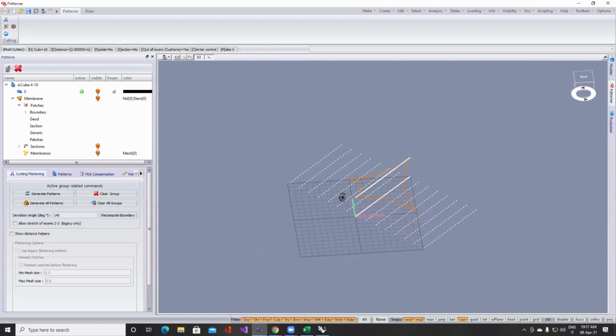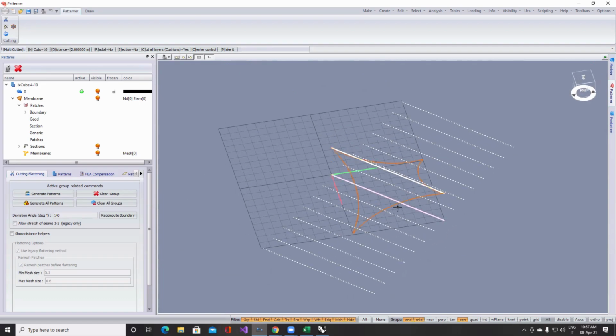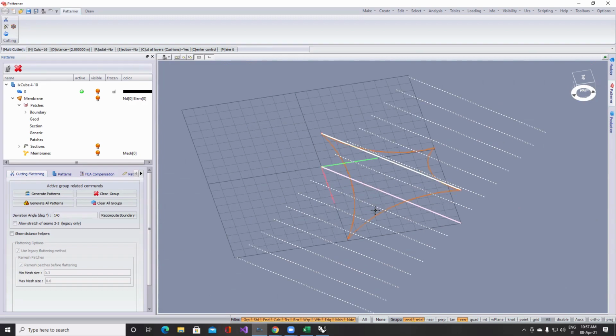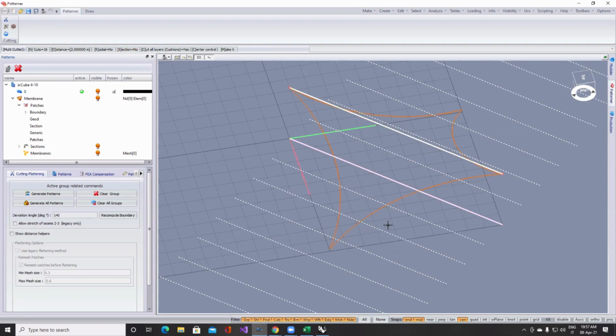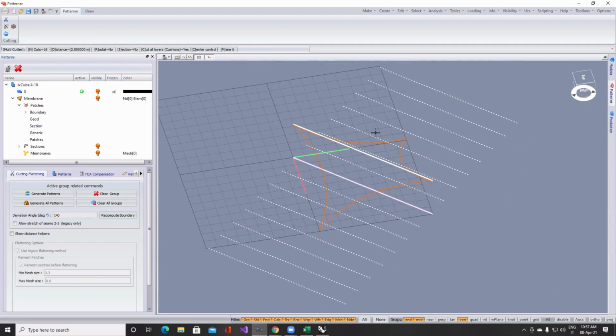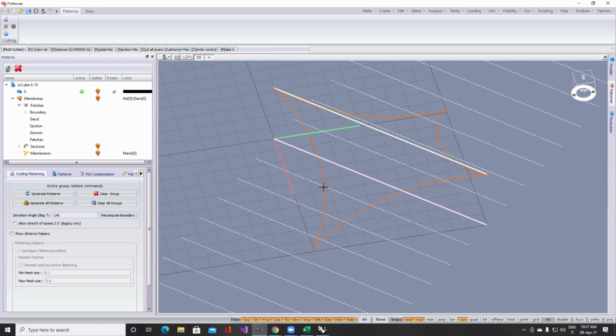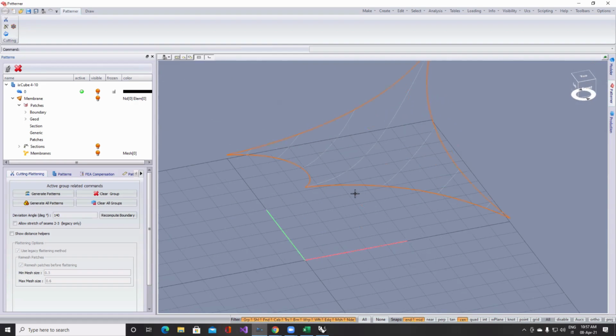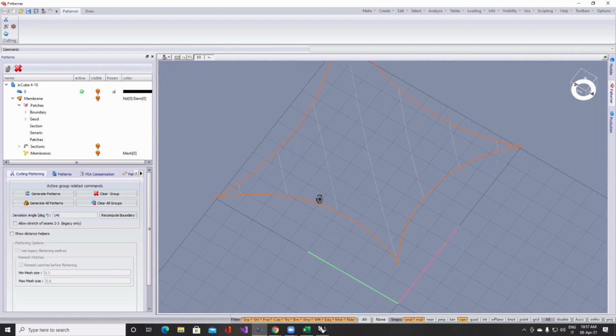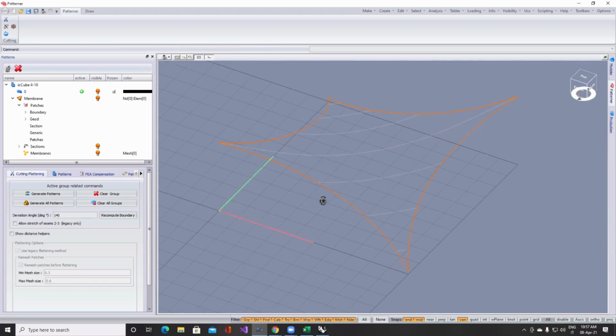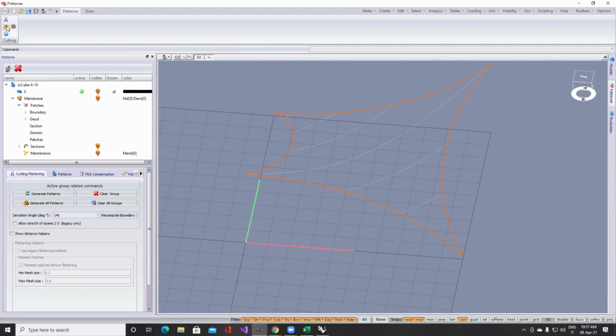In this case, we are defining one cut, and he's making a parallel offset of this line. When we click make, if we have the option section no, what will happen? The software will make a number of planes, will detect the intersection on the edges, and then will generate a geodesic curve. I will click on make, and that's it. He has made all these geodesics. You see that they follow the surface. Okay. This is the second option, multi-cutter.